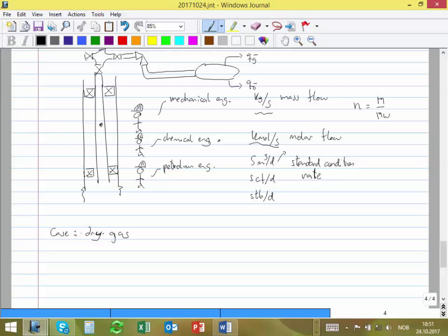Remember, this number is very convenient to calculate revenue, to calculate how much the well is producing. But it's not convenient to calculate friction losses, delta P due to friction. This is a function of the velocity in the pipe, if we see the pipe from the cross section. So it depends on the Q, not at standard conditions, but at local conditions. It's like an inconsistency: we are all the time working with the wells at standard conditions, but then to calculate pressure drop we need the real velocity, the local conditions. So we have to find a way to transform very quickly between the two.